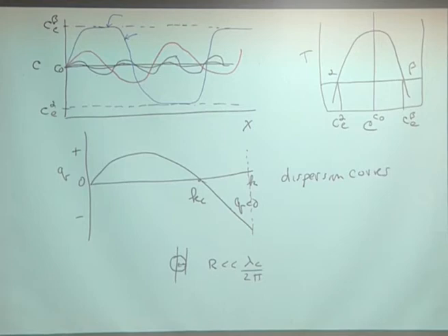Would you see spinodal decomposition? Probably not, right? And so this wave number here kind of gives you an order of magnitude length scale. If the domain is too small, then you might not see spinodal decomposition. That's a very hand-wavy kind of way of using these dispersion curves. You can ask more careful questions about, well, do you have absorption at the surface and other complicated things that might come into play. But it kind of gives you some idea of the importance of these length scales.